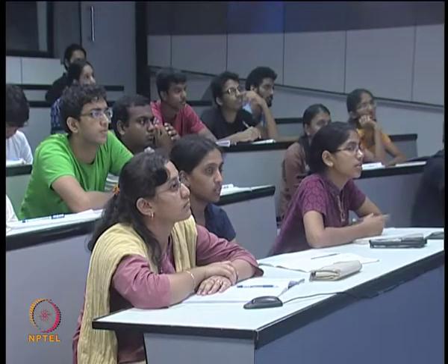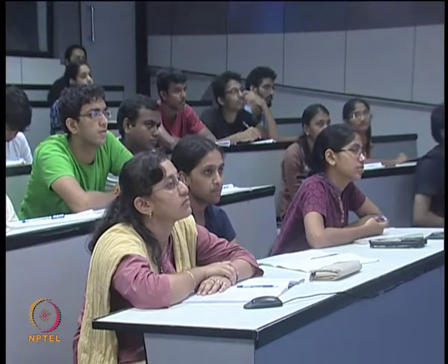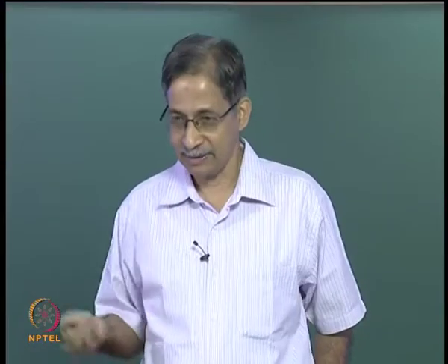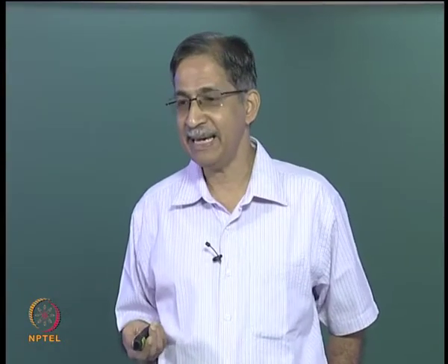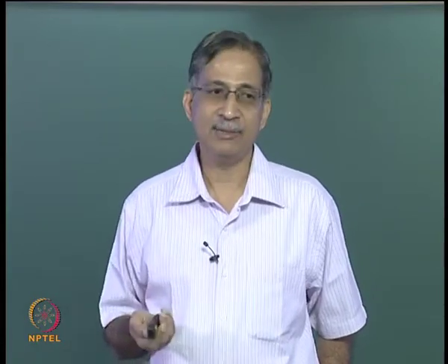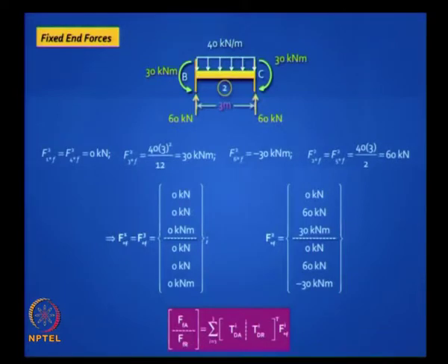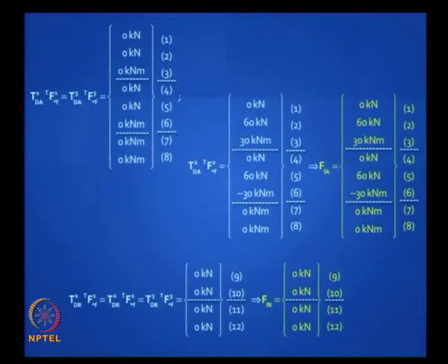You convert it to, you want to get it for the whole structure, right? You want the FFA and FFR vectors. How do you do that? TD transpose. So that contragradient principle works, and you can do one element at a time and sum it up for the 3 elements.